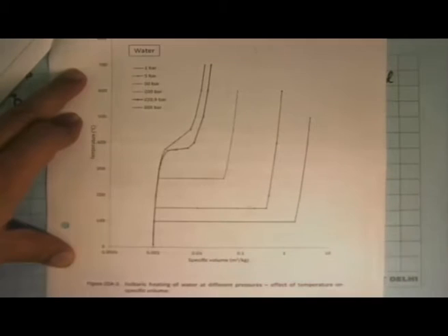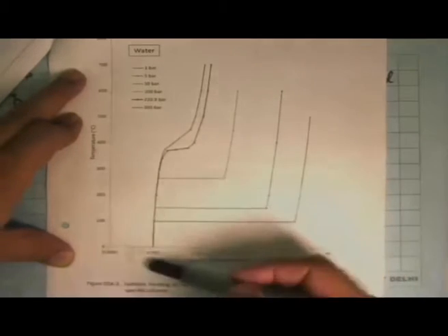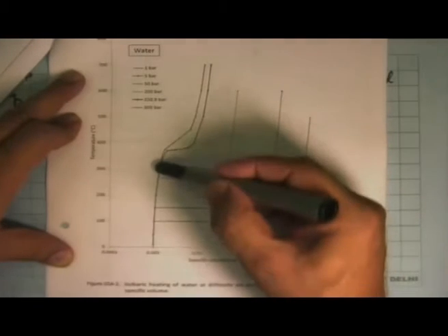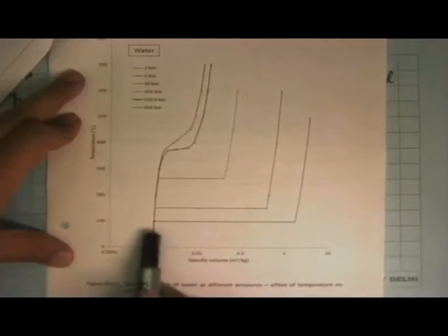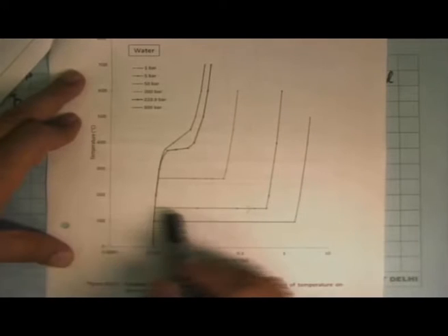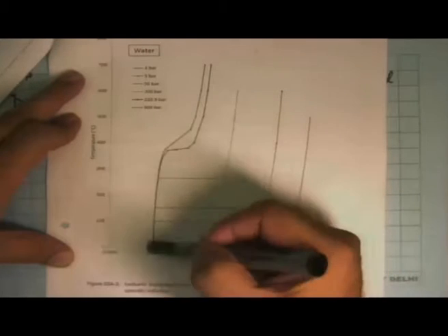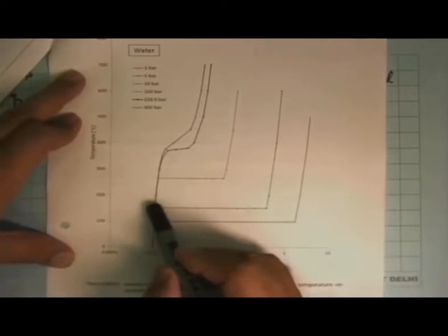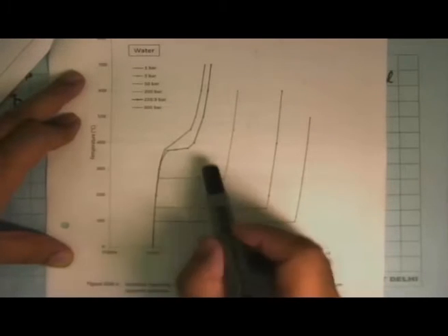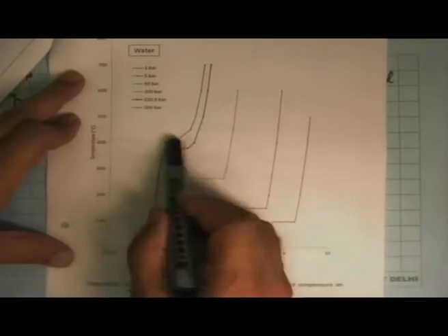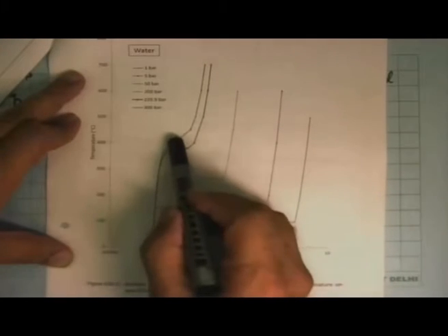And what you see here is what I was just mentioning, that the way I made the drawing qualitatively, my freehand, is quite unrealistic in what the actual numbers are. You can see here all these points are practically on one another, that the effect of pressure all the way to 300 bar versus 1 bar, there is hardly any difference in the properties at low temperatures here. Only here that you start seeing some difference, but at 100 degrees Celsius, the effect of pressure has very, very little effect on the specific volume. That's why all these have collapsed on one. These are all the saturated liquid points, and I didn't draw the complete thing, but you can draw this point here, get the saturated vapor line, saturated liquid line, and there is the critical point.